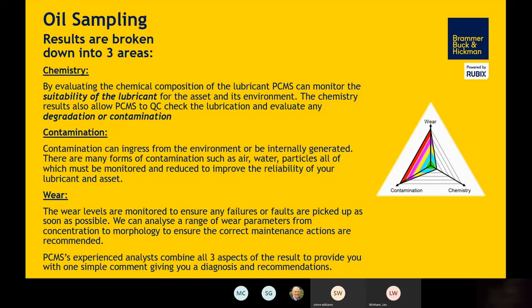And then there's wear. This is generated internally due to friction, abrasion, or erosion between moving surfaces or from corrosion. We look at the size, shape, and material type of particles within the oil sample to suggest which part of the component is wearing and how.